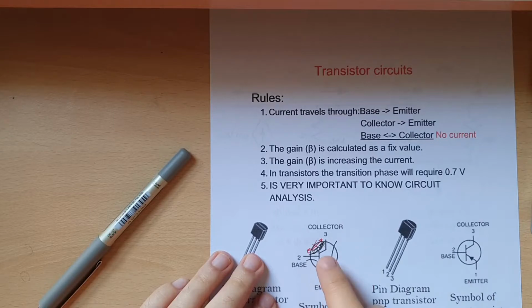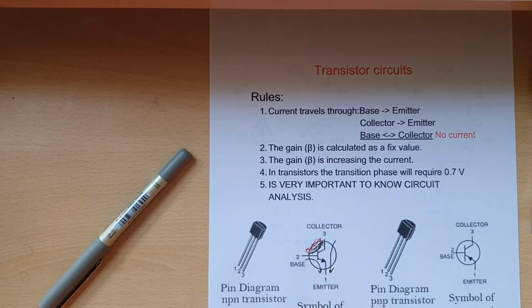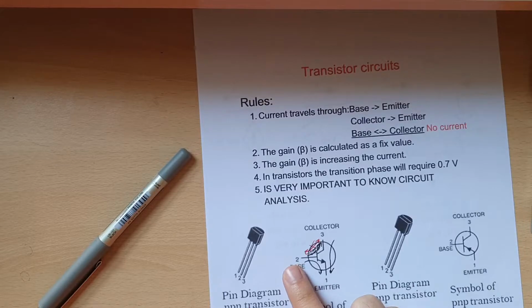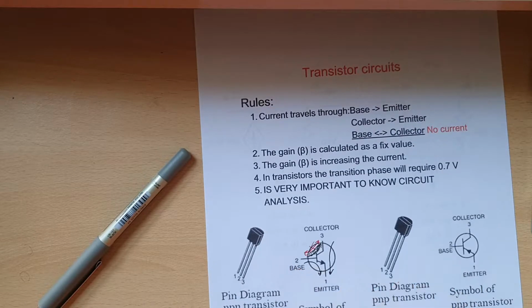And that's why transistors are also used in logic circuits very often. You may think, well, why do you use a transistor in logic circuits? Because if you want the signal from the top to the bottom anyway, you can just use the logic gate. And yeah, you can use the logic gate, but you need to think about that logic gates also have a fixed value too. For example, if you input here 5 volts with the logic gate output, logic gates cannot go higher than 5 volts. If they go higher than 5 volts, they just simply explode and burn. Or it cannot really generate a lot of current either, because of the same reason.